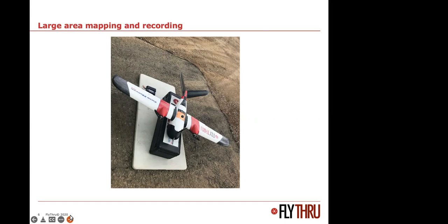Obviously, we're not flying in a straight line. We're never doing 300 kilometers. We are flying ups and downs, normally in 500-meter swathes, carrying the camera, doing overlapping imagery. And we use this a lot for doing mapping in and around the roads and rail network. It has twin motors, so if one of the motors fails, it's not going to fall straight out of the sky. If both motors fail, we're able to glide it away from any structure or persons or traffic. So that's why we use that type of drone.